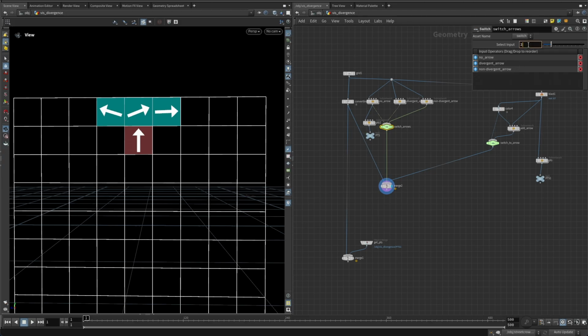The other method is to take the difference between the initial velocity, which is the initial average velocity of the particles, and the non-divergent velocity, which is a bit different. You take the difference between them and add it back to the existing velocity in these particles.